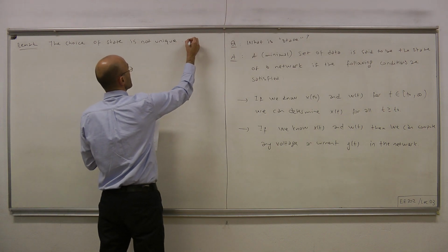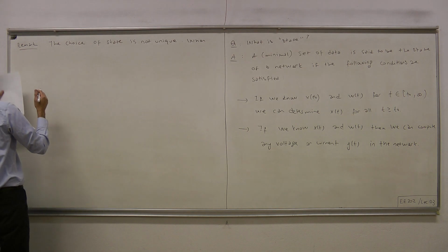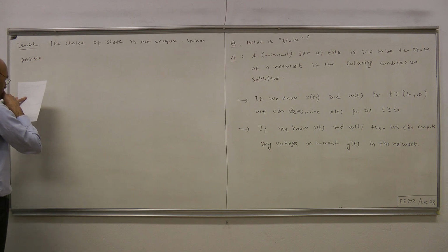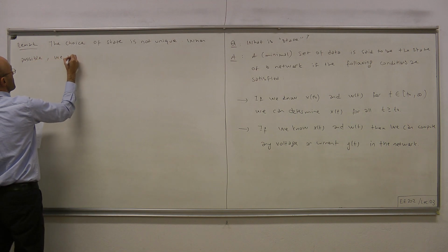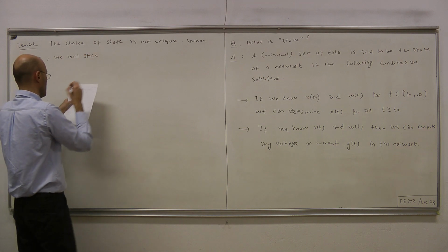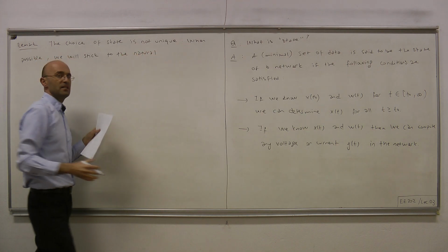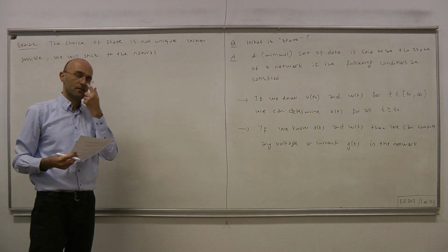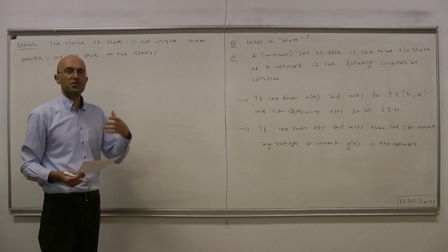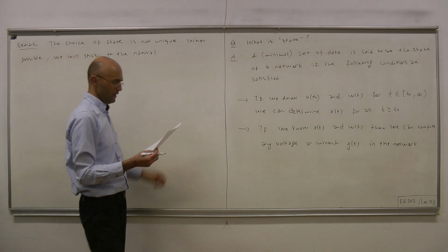When possible, and most of the time it is possible, we will be using the natural choice, by which we mean capacitor voltages and inductor currents. For mechanical systems, usually natural choices are the positions and velocities of certain links, let's say.